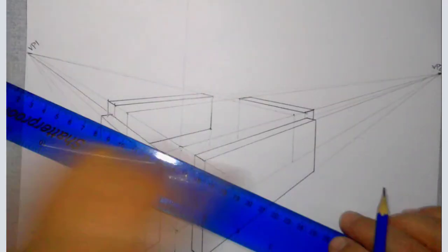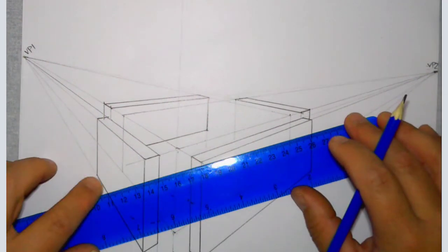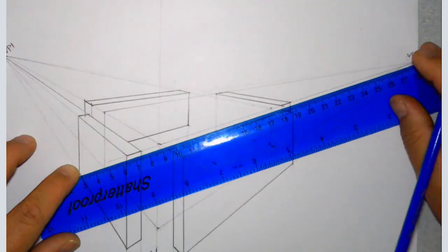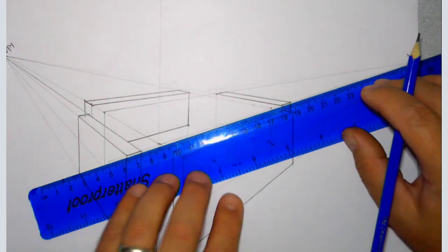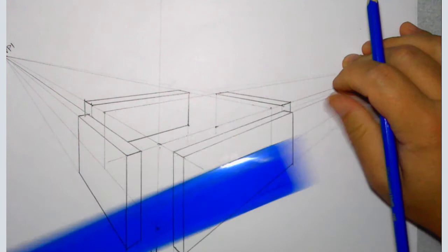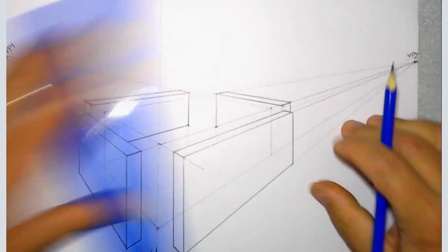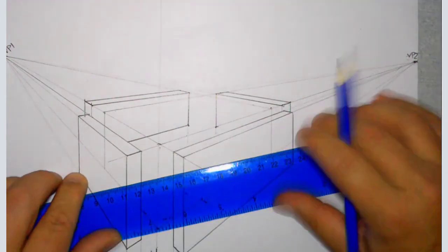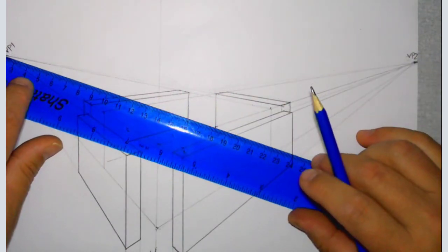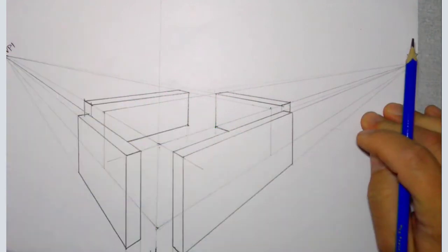And then the next one here, we can make a decision based upon, well, it would either be that edge there, or because of the view I've got, is this corner here, we're lined up with that, heading off to VP2. That corner to VP2 is going to be there. It happens to coincide with another line, but that's just a coincidence really. Okay, so I took that back corner, I plotted to VP2 to give me that line, and now from that point, from VP1, I'm going to project forward until I meet the next face. That gives me that point there.